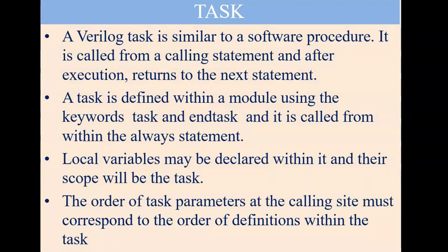Now we'll come to the definition of a task. A Verilog task is similar to a software procedure. It is called from a calling statement and after execution returns to the next statement. A task is defined within a module. Remember, a task is defined within a module using the keywords task and endtask. Beginners should remember this. Every task will start with task, of course the task name, and it will close with endtask. Whenever I start with a task, it should close with endtask.